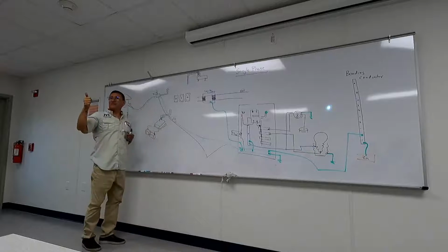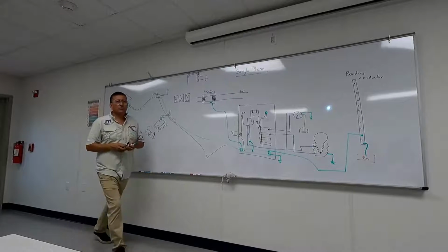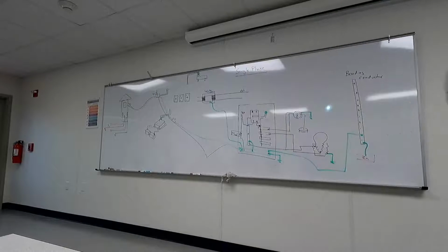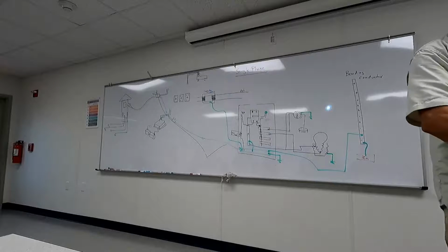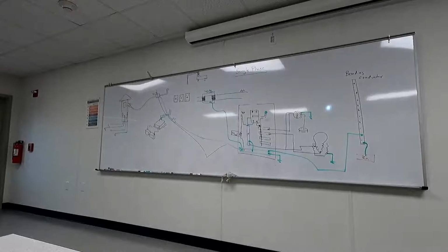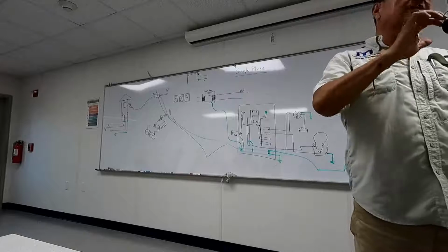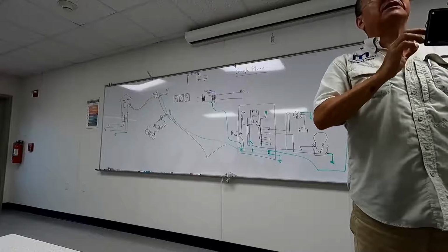Was that clear, the reverse polarity? Okay, good. Now we are going to continue with single phase. I am going to replace the traditional selector switch with three breakers. Ready? Because this one is too expensive and the connection is not easy. You can make a lot of mistakes here.